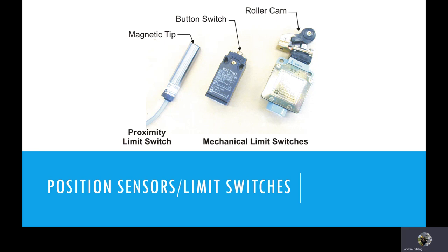For instance, if I had a robot that is welding cars, I could have it programmed to weld the frames of Toyota Camrys on Tuesday and Toyota XLs on Thursday by simply changing the program, and I wouldn't actually have to change any of the plumbing of the fluid. So you'll find that the proximity switches are used a lot. And a lot of times they'll use the magnetic tip. And as that cylinder goes by and the piston comes up close towards where this proximity switch is mounted, it will flag it.